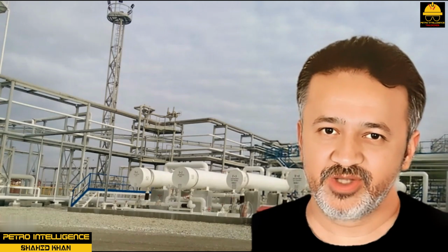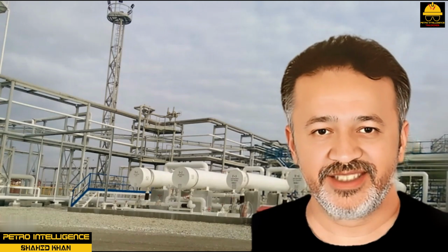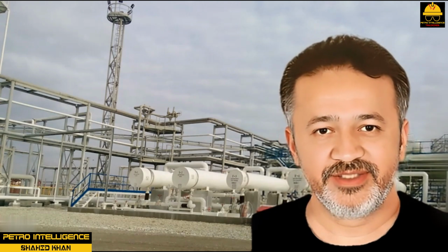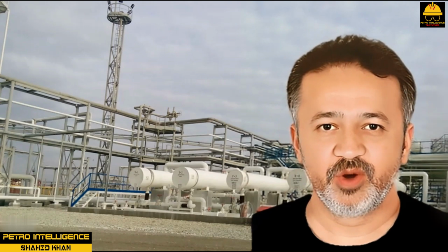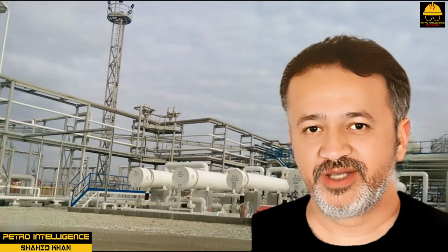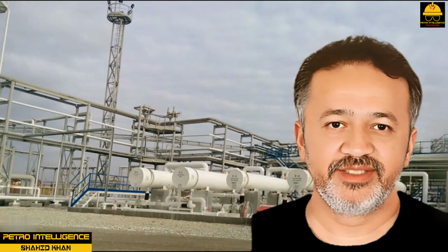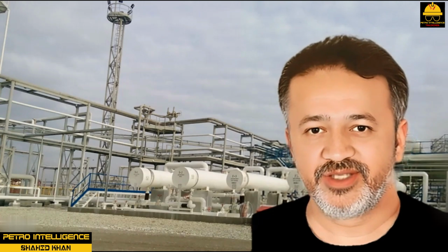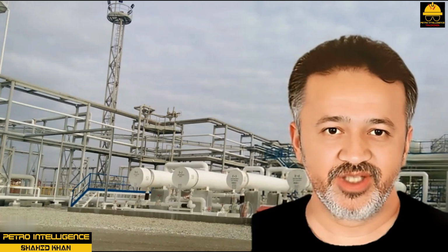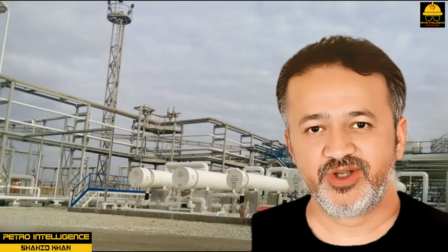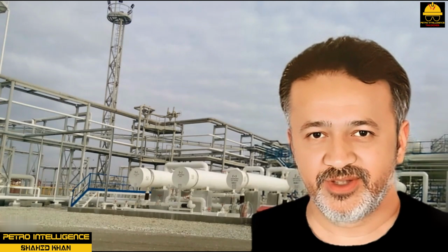Shell-and-tube heat exchangers are designed to handle high flow rates in continuous operations. Reboilers are used to maintain heat balance in distillation columns. Kettle reboilers and thermosiphon reboilers are the types most often used. Condensers are typically shell and tube heat exchangers often used in distillation columns to condense hot vapors into liquid. The three methods of heat transfer are conduction, convection, and radiation. Conduction and convection are used in heat exchangers, but radiation is not used.